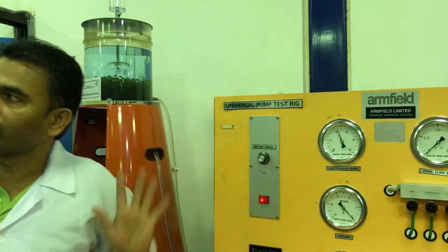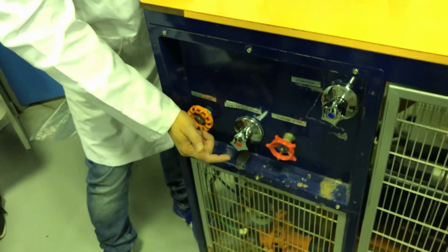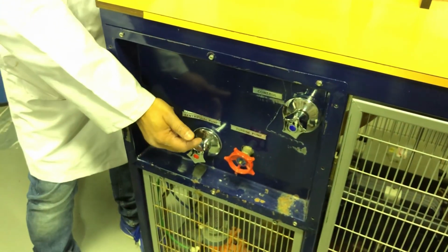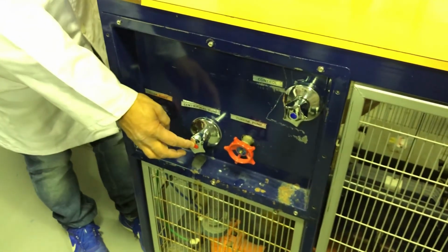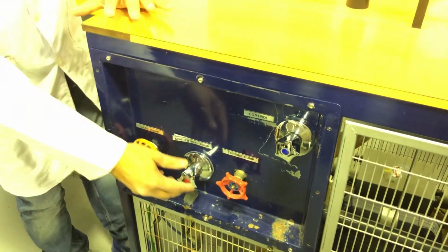Okay, now next reading. It is important how to do this. Now our speed is constant. We are not going to change the speed. We are going to change the Q, volume flow rate. So I will operate this for the centrifugal pump. Actually we can operate this, but we can operate this also, no problem. So we'll operate this, reduce the discharge. Now it is full discharge. So reduce the discharge